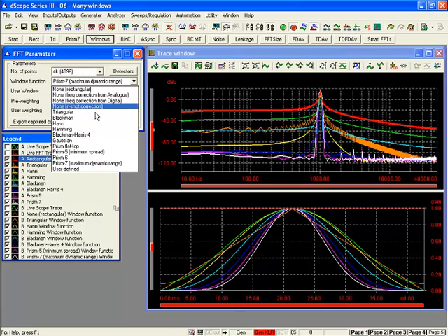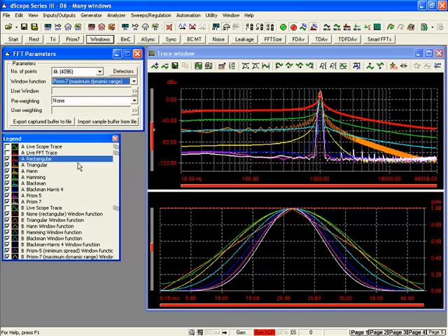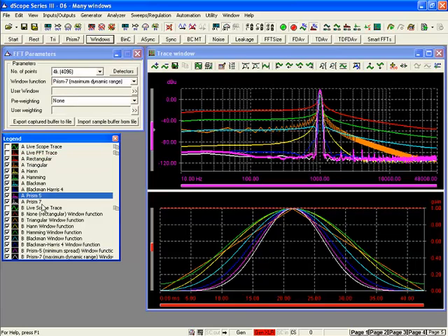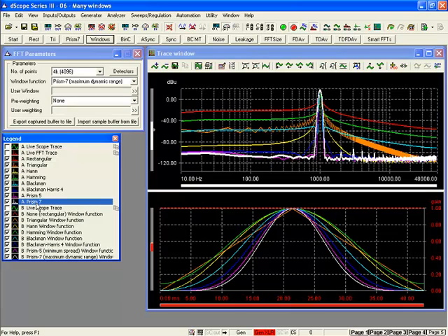And what we at Prism Sound have done is designed a series of window functions, through some fairly sophisticated optimization algorithms, that give you the best trade-off of analysis dynamic range and spectral leakage, specifically for audio applications. And this pink Prism 5 and this white Prism 7 window are the two window functions that we use most commonly in audio measurements, at least when you're using the Prism Sound tester measurement solutions.